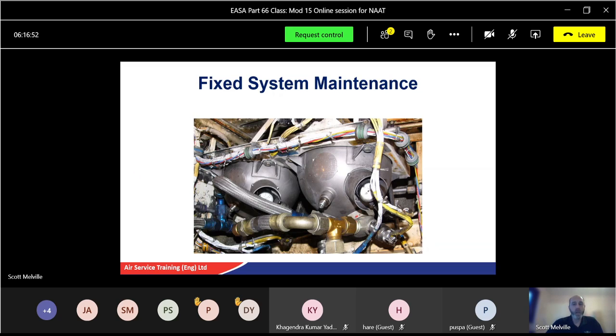There should also be a weight check. Once a year, these will be weight checks, just like normal handheld extinguishers. So they will be weighed, because they might be leaking and might not show discharge. If they've got a pressure gauge, that's fine, but the pressure might be fine and it could still be leaking. The weight check makes sure there's no loss of extinguishing agent.